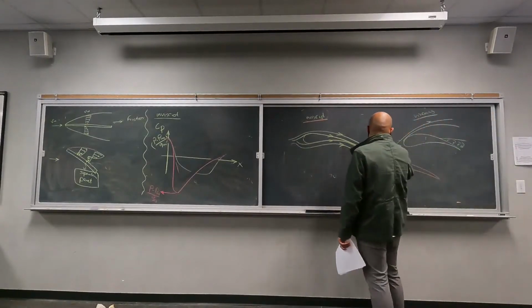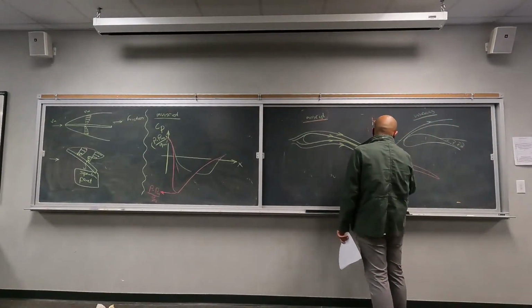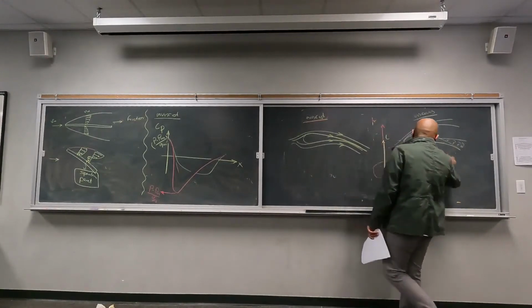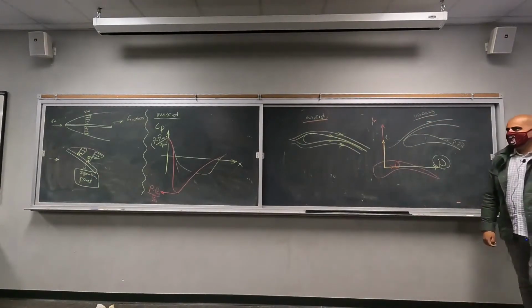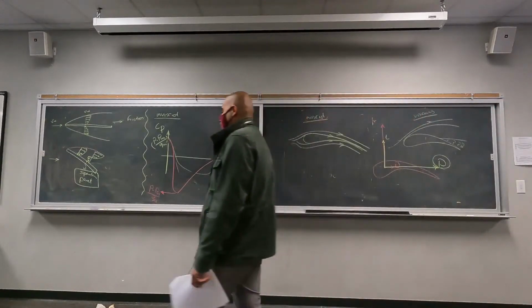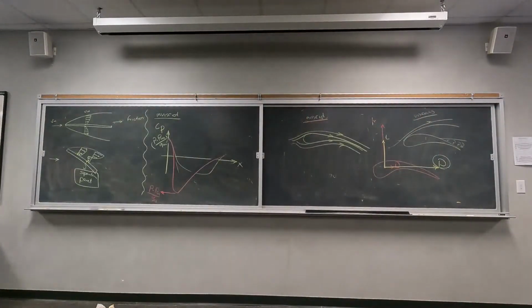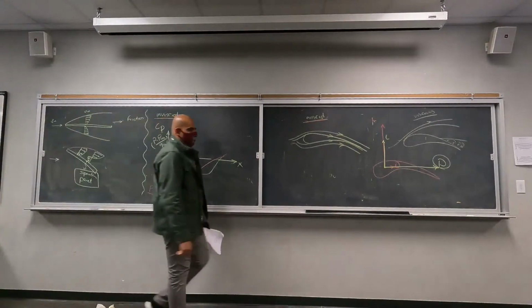But in the real case, what you have here is actually a huge contribution of pressure drag if we have already surpassed the stall condition, and a huge drop in the lift. So that was just a brief qualitative analysis of what is going to happen to your pressure when you include the effects of viscosity.